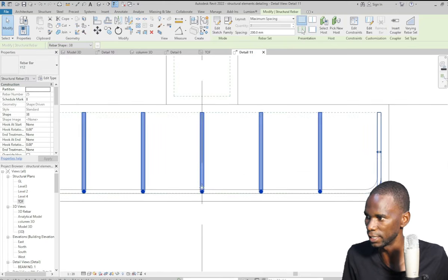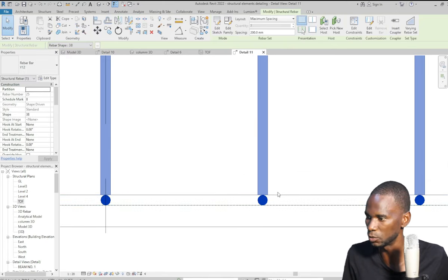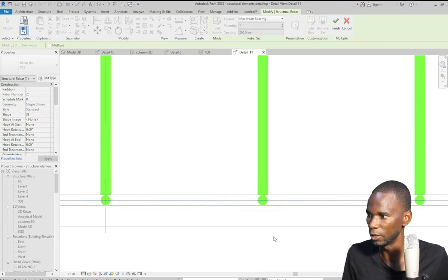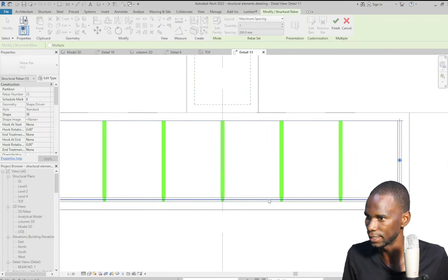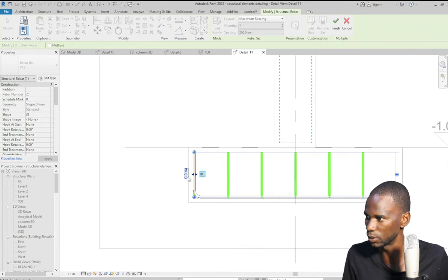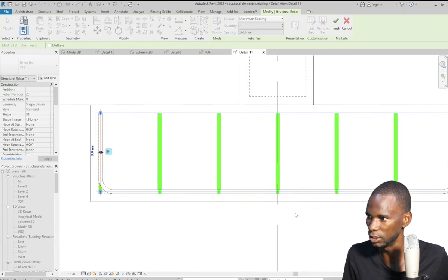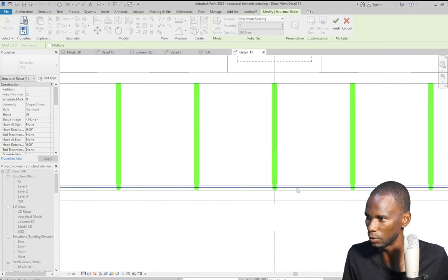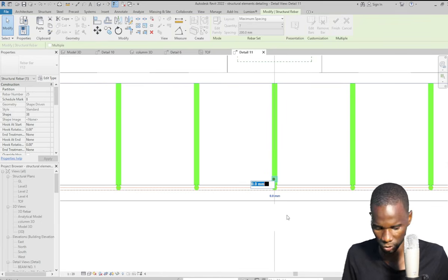don't want the interference there for the rebar, so I want it to be on top there. So there's a tool that you use which is called Edit Constraints. Click on it, okay, then select the edit constraints. As you can see, you are able to change it from there by offsetting. So I'll just select the base, then click the number there. We have zeros, then I'll just start with 12.